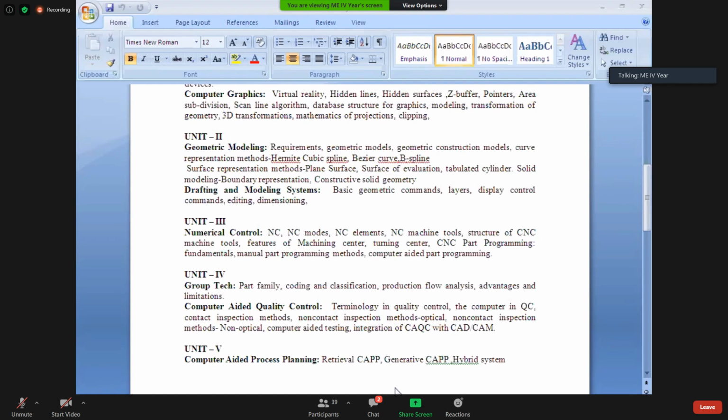So these values you evaluated in ANSYS, but in this particular SolidWorks software, and CATIA also, the mass property value calculations, we can give the values and we can check them. Suppose we give some value to some material or some model, then once you apply the loads, it is damaged, or the result shows that there is some problem in the material or the structure. Immediately we can go to the part model and change the material or the dimensions. Either can be done on the part model, and you can update it and repeat the analysis results.